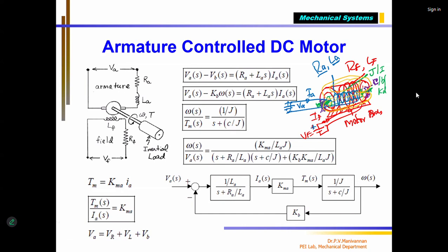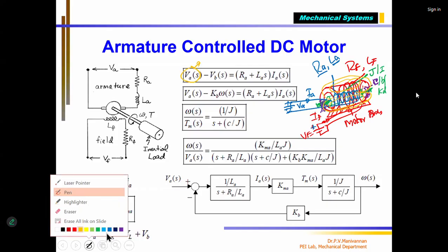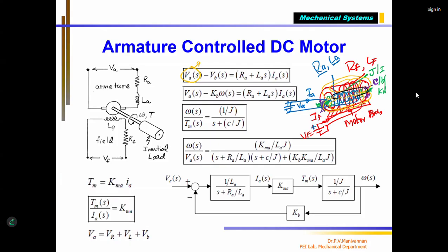Okay. Similarly, we are supplying current to the armature. The armature also we are supplying with VA. So because of that, the armature also produces some flux. Okay, let me show it in black color, maybe easier. So this coil also produces. Please note that these are magnetic fluxes. Correct? They are invisible. They can penetrate air and most non-conducting material. So that I call phi A. The other one is phi F. This is nothing but phi F.